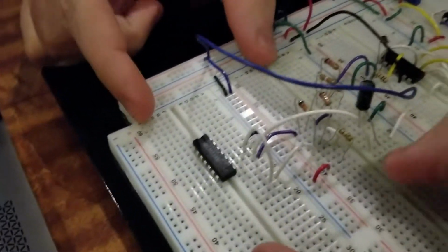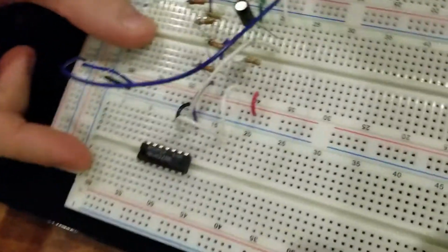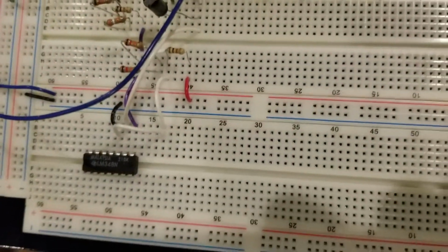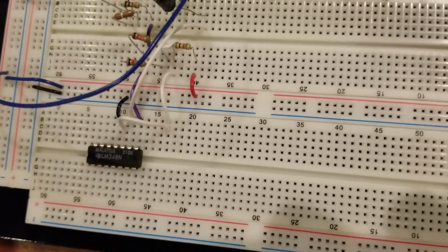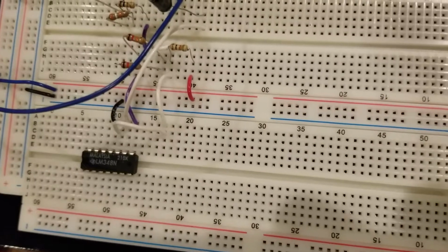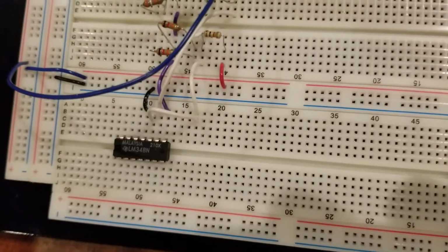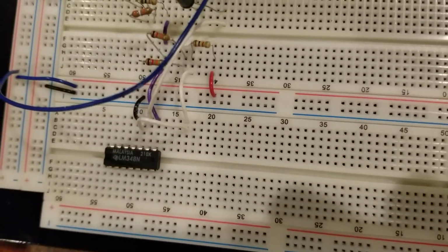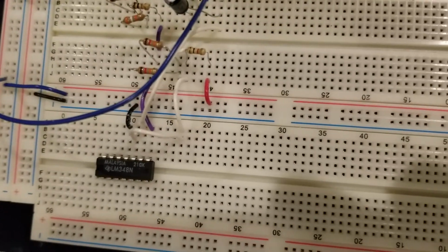So next is our second sub-circuit for the VCO, which is the Schmitt trigger, and is set up on this portion of the breadboard. So what the Schmitt trigger does is that it is fed in some kind of voltage, and then depending on two threshold voltages that the Schmitt trigger is designed with, it outputs either a high output or a low output, meaning that those are the two states for the Schmitt trigger.